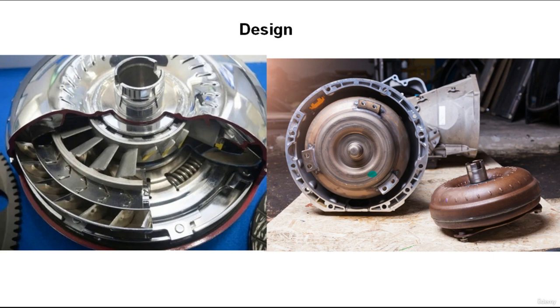torque converter shell. A heavy flywheel is not needed because the mass of the torque converter and the flex plate work like a flywheel to smooth out the intermittent power strokes of the engine. The flex plate or torque converter is surrounded by the ring gear for the starting motor.